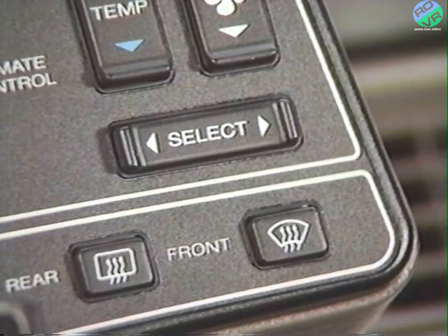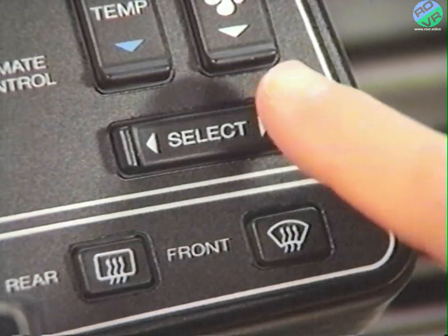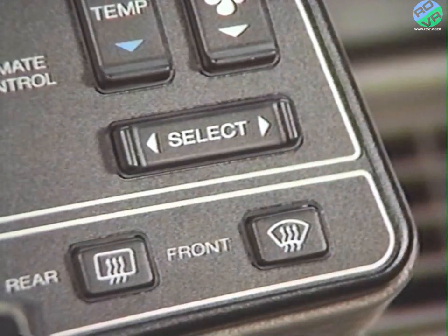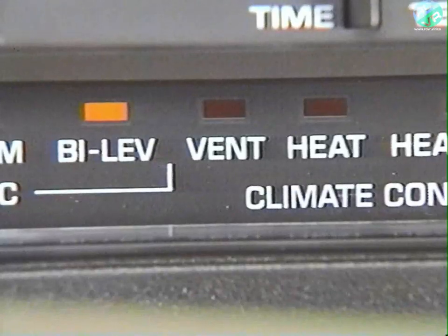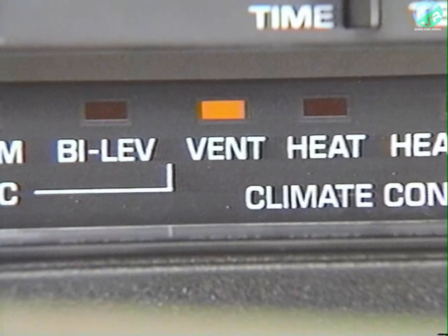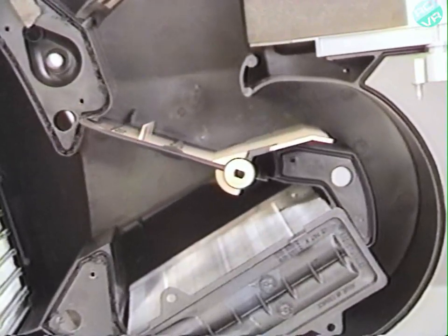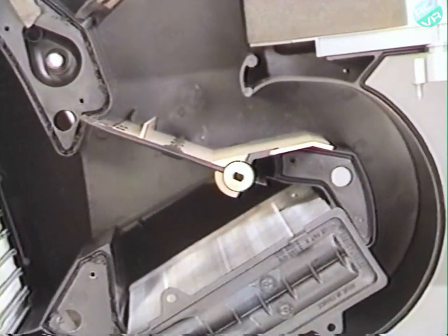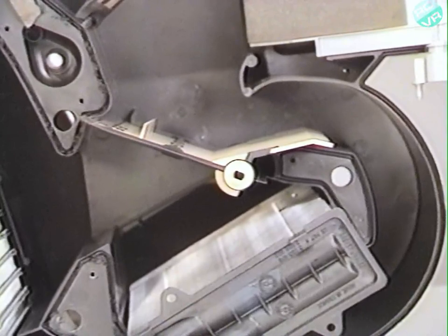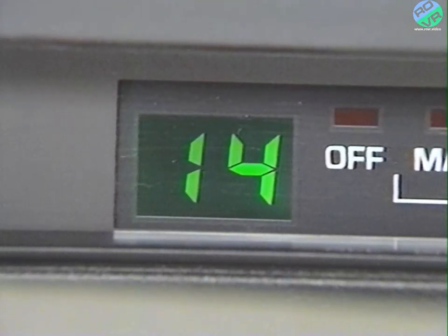Now, to enter sub-mode 2 of M2, press and release the mode select switch right arrow. At this point, the display will change to vent, and the ACM will move the air mix door to the stop at the full hot position, or to a position 45 degrees from the center of travel, whichever occurs first. The temperature display will again indicate the feedback voltage.